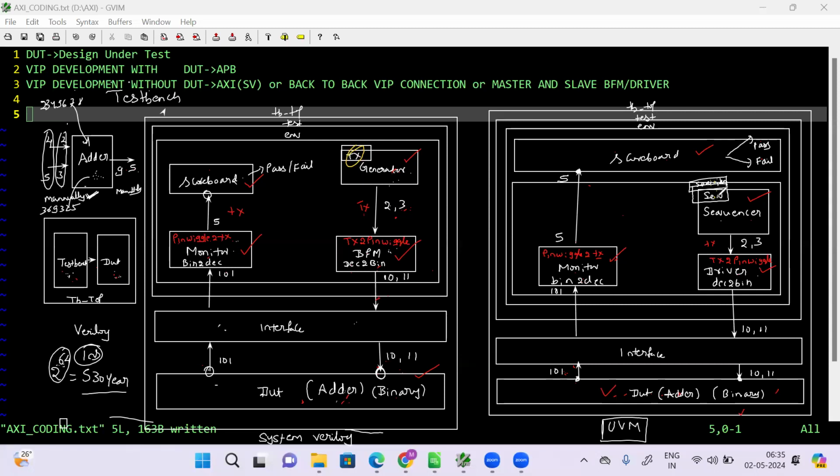Hello, Nitish. Okay. Sequence is a different item and transaction is a different item, right? See here, actually in SystemVerilog you call it a transaction, and the same thing you call sequence item and sequence in UVM. But if you see from the diagram or an internal perspective, they are similar only. You can equate your transaction to your sequence.